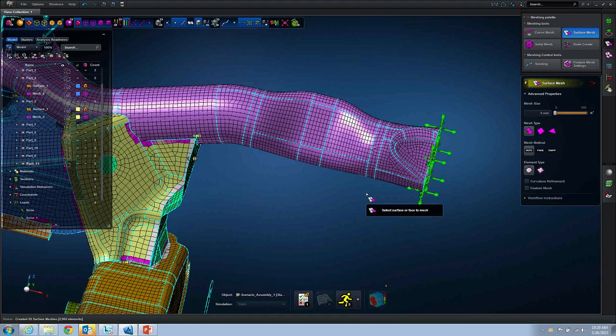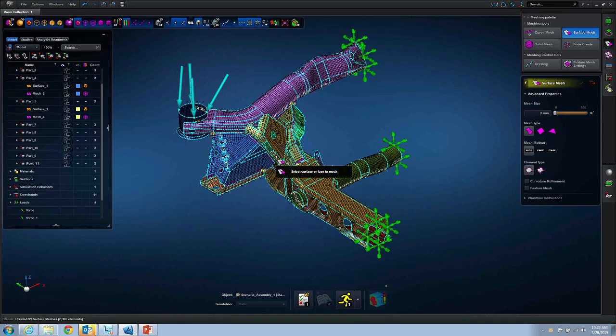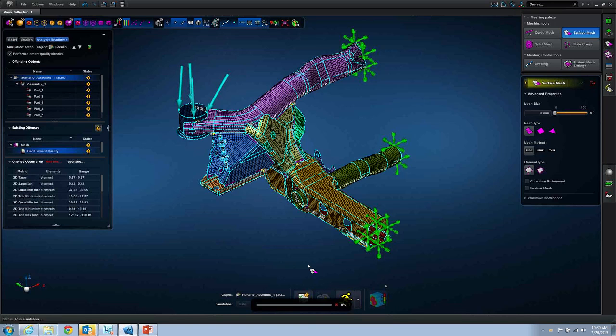So in this one, we did quite a bit of changes. Number one, we modified the design of another part. Number two, we increased the thickness of this part, and we modified the area mesh here, and we also changed the orientation of the vectors. Now, if there were any things that violate the mesh condition or the assembly condition, we would have seen the red mark here saying that some things are broken in the model. And now, since everything seems to be intact and it's solver validated, we can click this button to rerun the simulation with all these changes.